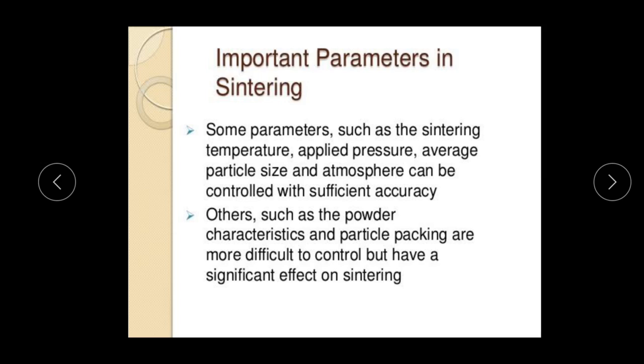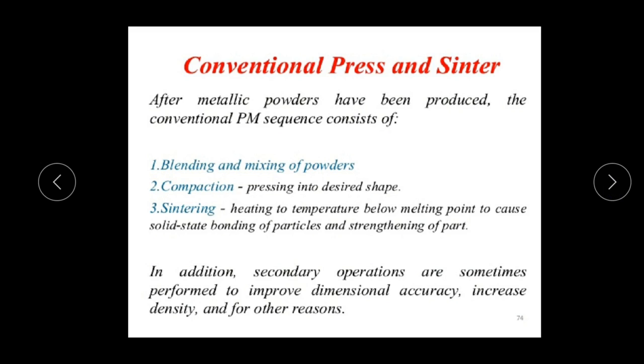Some parameters such as sintering temperature, applied pressure, average particle size, and temperature, atmosphere can be controlled with a sufficient accuracy. And others such as powder characteristics and particle packing are more difficult to control but have a significant effect on sintering. Yes, let us discuss conventional press and sintering.